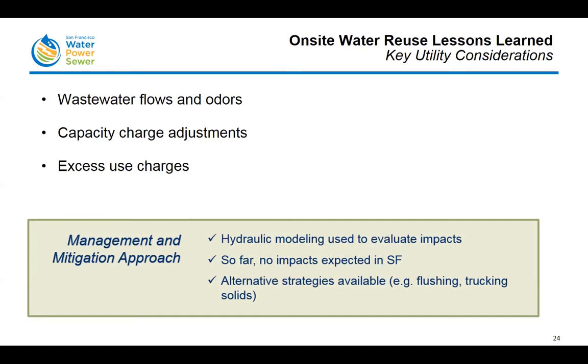However, if there are expected to be impacts to flows and odors, we provide alternative strategies to projects to deal with those potential impacts. That can include flushing of the sewer laterals, as well as, instead of discharging solids to the sewer system, having a Vector truck come and pump away that sludge and take it to the wastewater treatment plant.